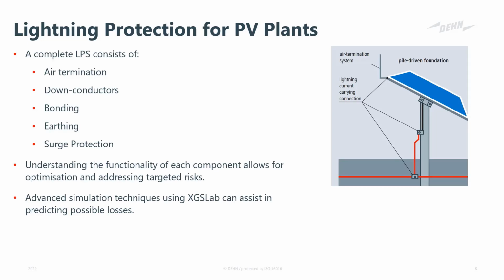So you can see firstly the external portion of it. We have an air termination rod mounted at the back of the PV modules. There are different ways to do this. It could be very custom. So we do this typically to match the wind load requirements and the wind load ratings of the PV system itself. We take care that separation distance is maintained and kept at the corner so it doesn't flash into the PV module if it gets struck.